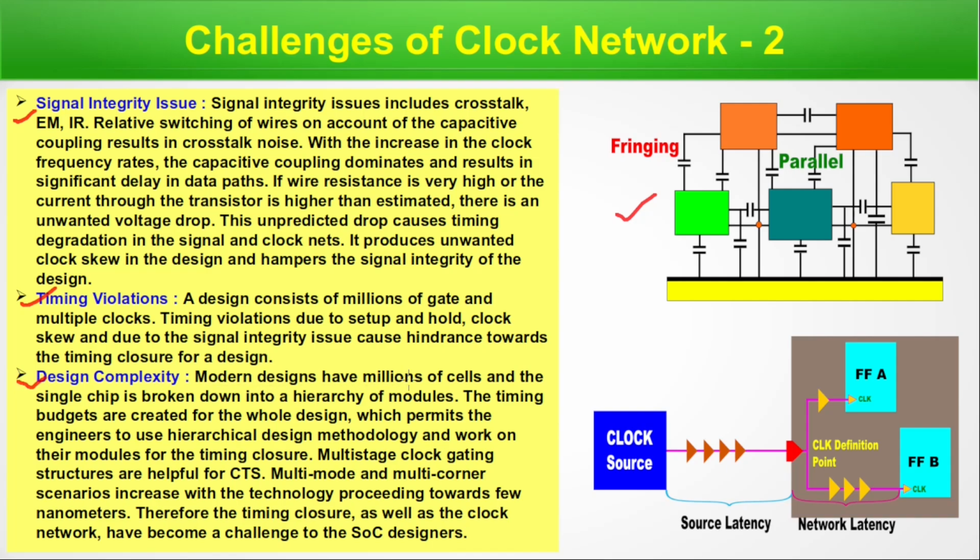Now, design complexity. Modern designs have millions of cells and the single chip is broken down into a hierarchy of modules. The timing budgets are created for the whole design, which permits the engineers to use hierarchical design methodology and work on their module for timing closure. Multi-stage clock gating structures are helpful for CTS. Multi-mode and multi-corner scenarios increase with the technology proceeding towards few nanometers. Therefore, timing closure as well as clock network have become a challenge to the SoC designer.